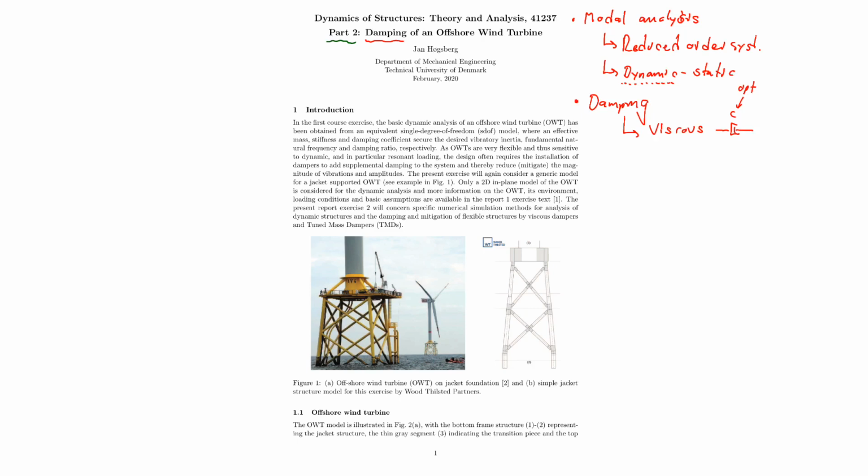damping into our structure. And the next approach, we will then introduce a so-called TMD, a tuned mass damper. That is a spring in parallel with a dashpot supporting a supplemental mass, and then we have our structure over here that vibrates. So in this case, the damper suddenly becomes a resonant damper because we have an interplay resonance.